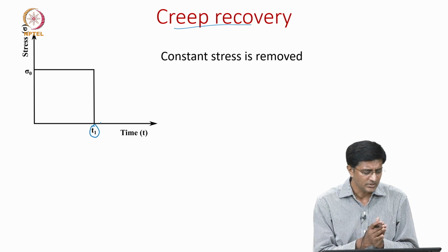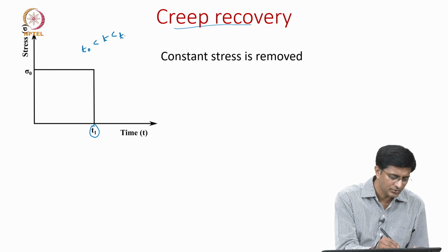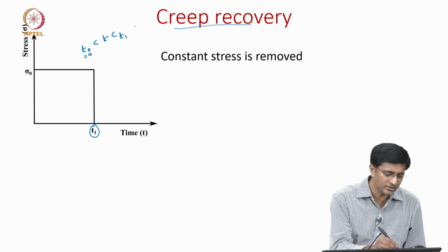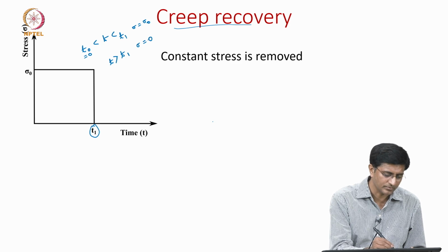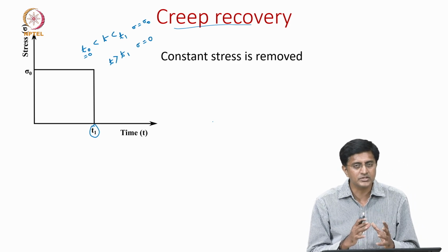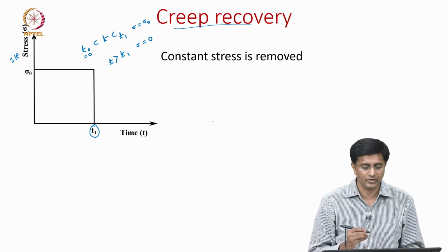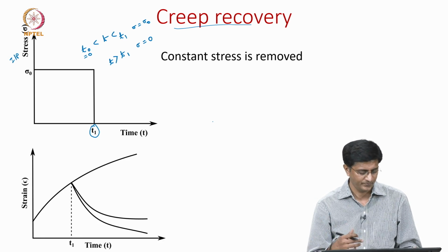Let me repeat it one more time: between times t naught and t1, where t naught is our time 0, we have sigma equal to sigma naught, and if time is greater than t1, the stress goes back to 0. So this is the loading or the input we apply for a creep recovery test. Now, let us see how the response is.